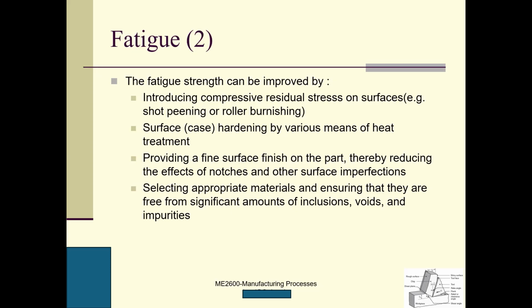Then you elevate the temperature. After you elevate the temperature, a lot of carbon atoms from the liquid, solid or gas will come to the surface of your workpiece. As a result, the hardness of your workpiece will be increased, and at the same time, compressive residual stress will be induced.